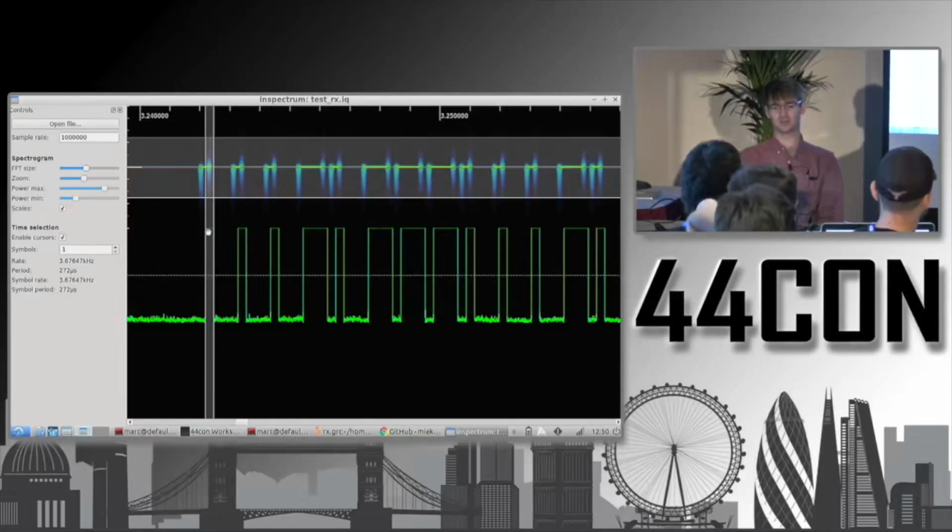And usually, what you want to time is the shortest transition that you see. So you see here we have some symbols where the high period is shorter than others. You want to try to time the shortest transition possible, because that's likely going to define your symbol rate.